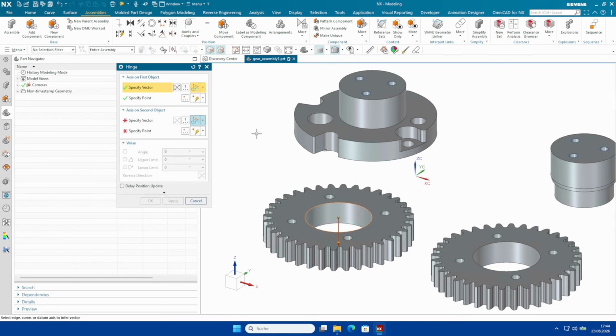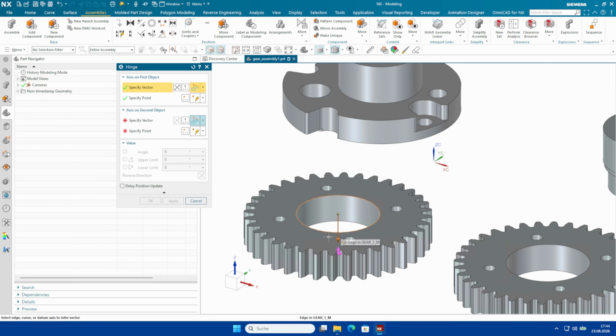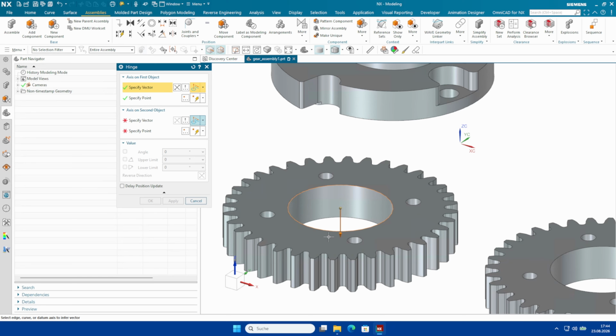If you want a point which is far away somewhere, you either have to use a cylindrical constraint instead of the hinge, or you have to reference a point in the sketch of a model and then change the reference set so that you can choose that point and align your model geometry to that point. But for now, for the simple hinge in this tutorial, I'm going to use the same point.